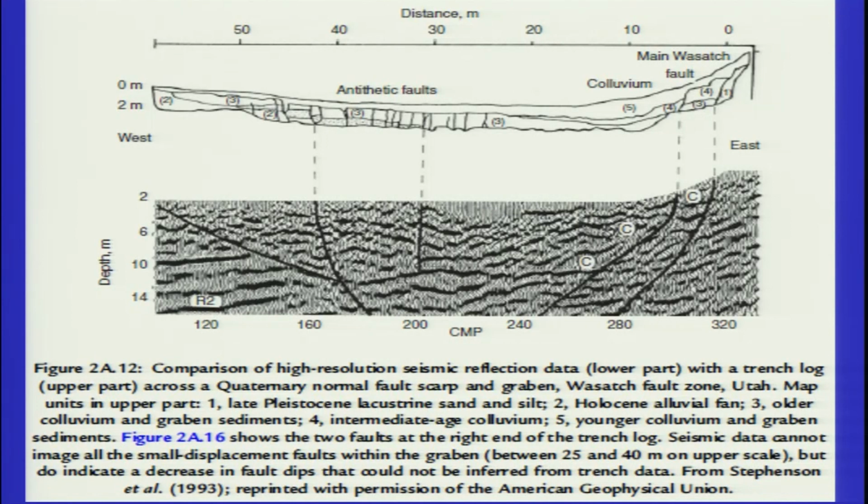Then you can also do high resolution seismic reflection and compare it with the trench log. So, the trench is hardly 2 meters deep, but with the seismic reflection you are able to reach right up to 14 meters or so.